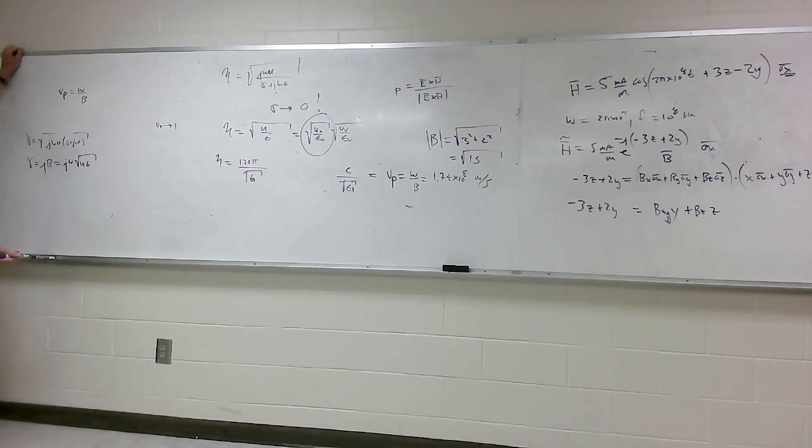You just watch this for a second. It means beta is equal to omega square root of mu epsilon. Can you all follow me? I'm not trying to go too fast, but I'm going to just show you that if this is gamma, alpha is 0 because sigma is 0. That means gamma is simply j beta, and when I put sigma 0, it means it's j omega square root of mu epsilon.